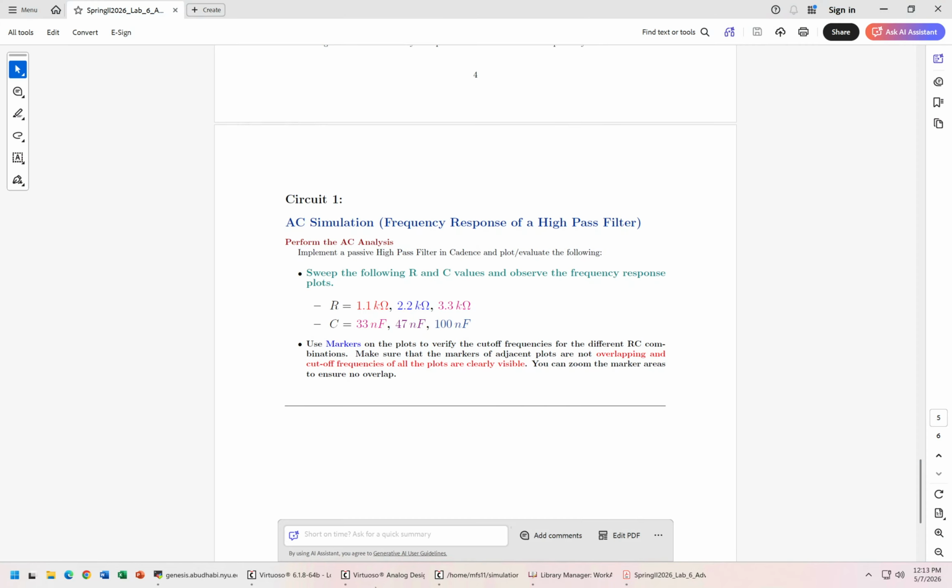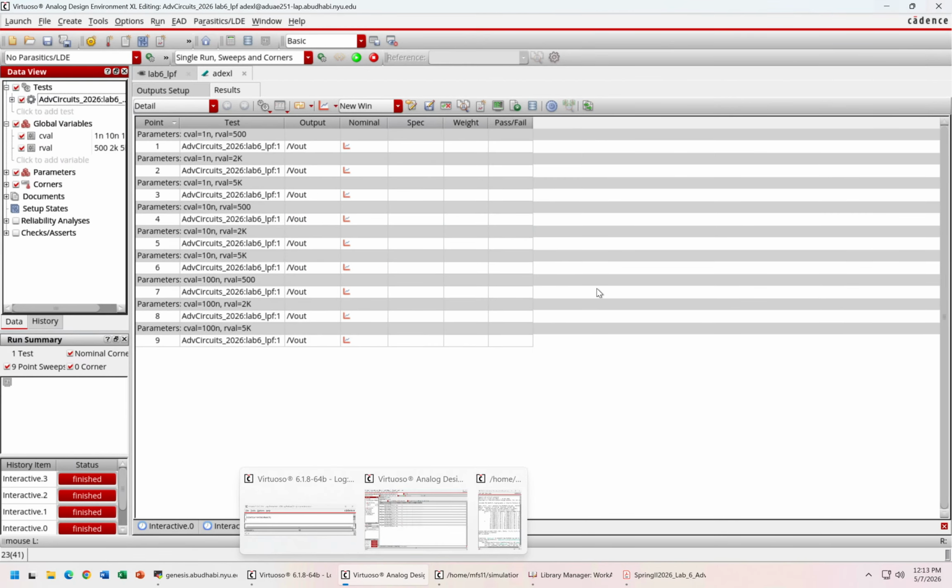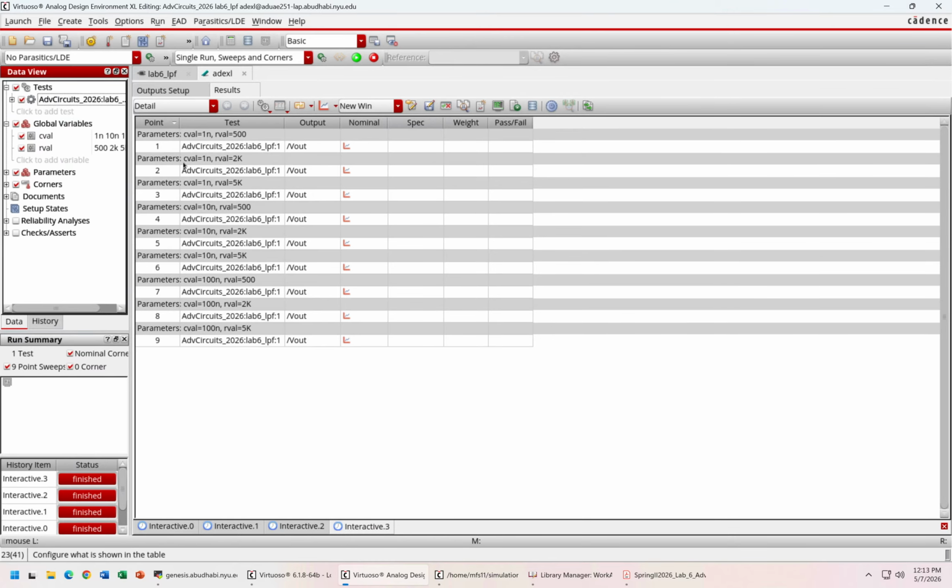And yeah, this is what we can do, and this is called the parametric sweep. This is very useful when you have to look at the system response against a frequency, when you're designing some system and you want to know exactly what my limitations are, how my system responds to what frequencies. Instead of changing values each and every time, like I've done in the beginning, like changing capacitor value from 1 pico to 1 nano, you can set the range of values.